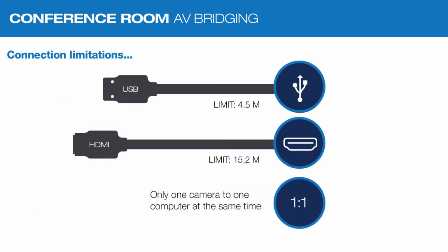And despite the length limitation, you might want to add some adapters in your cable, and that will just reduce your effective length even more, because you'll get interference and signal losses. For USB, you might need active extenders, USB hubs, and USB switches, and all of these can basically become a point of failure in your system.